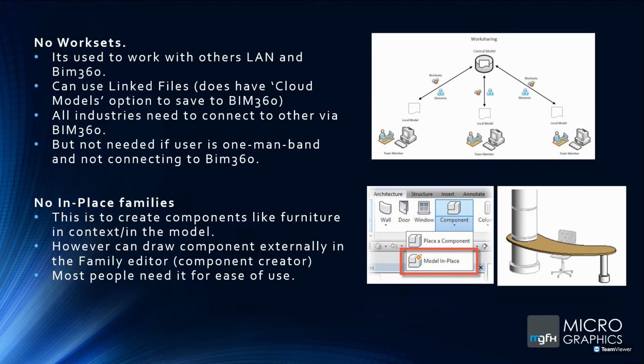There is one in-place family, and that's walls, where you can create odd-shaped walls as an in-place family. In saying that, you might create the desk in the wall category, and just give it a different name, that sort of thing.